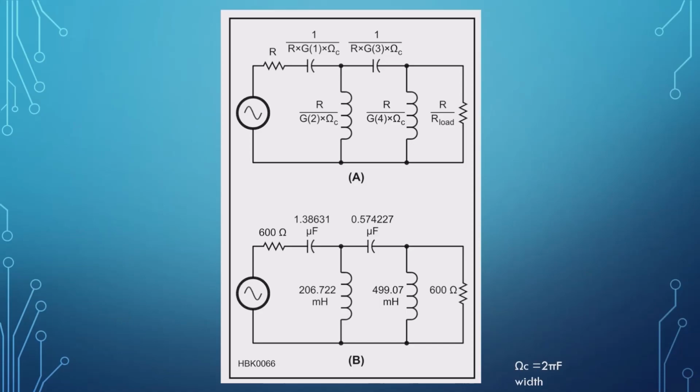You have to match it to the network. Yes. Radios are typically 50 ohms. A ladder line system with different antennas might be 400 ohms. The ladder line is typically 400 ohms, things like that. That's why you'd want to match your impedance, or you have to have a balun in there to match it. In our case, though, we're not talking about the output of an amplifier or transmitter going into an antenna. We're talking about this little processor module and clock system. Do we know the impedance of that? Yeah, that's at 50 ohms. Oh, it is. Okay. So we would design it at 50 ohms. Okay.